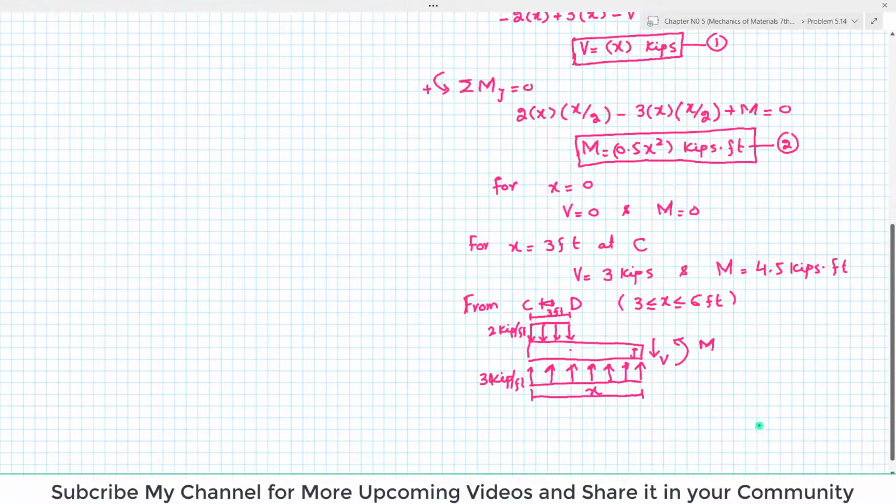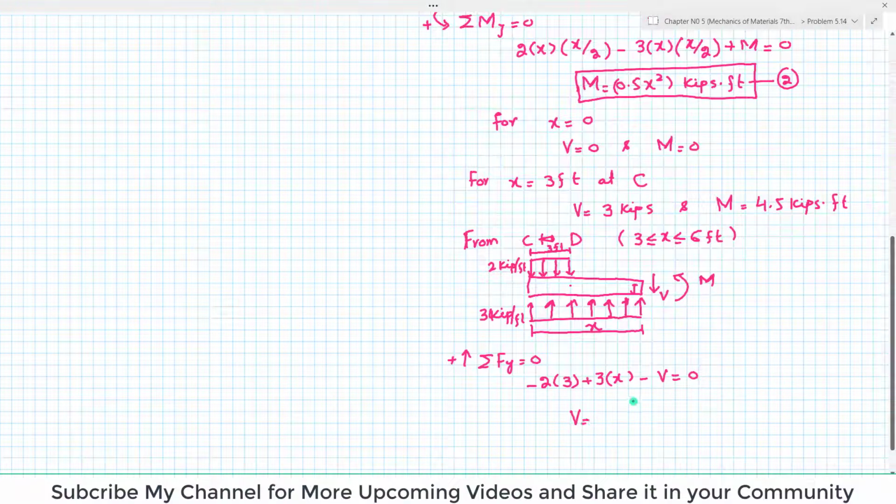Now we will find the equation of shear force for this. The sum of all forces along the y direction must be equal to 0, taking upward force as positive. So this distributed load 2 into 3 will be converted into a vertical force, and this is downward, so it will be minus, plus 3 into x gives the point load here, and minus V, their sum must be equal to 0. When you solve this, you will get the shear force V equal to 3x minus 6 kips. The unit will be kips. Let this be equation number 3.